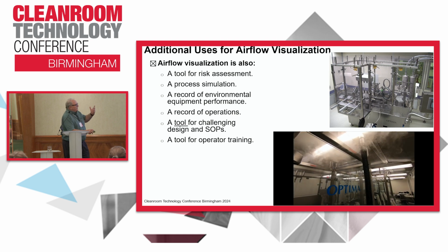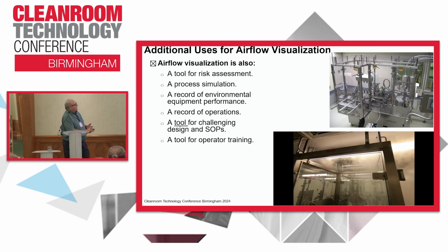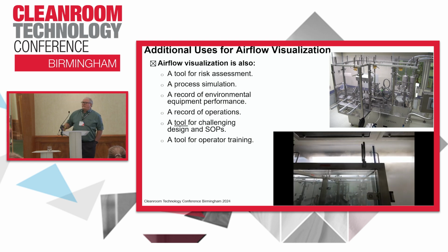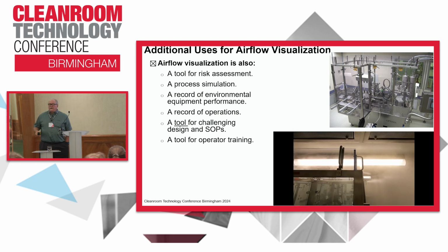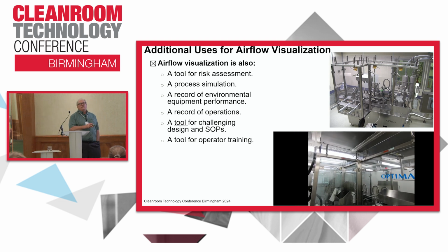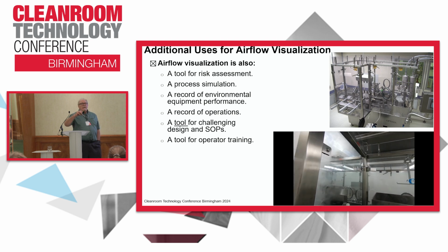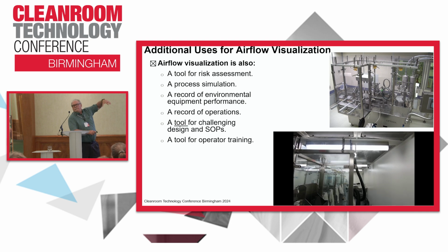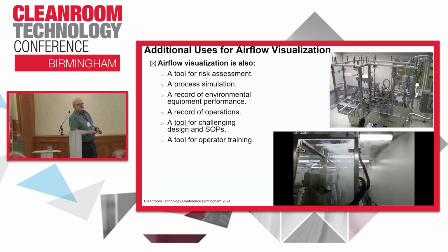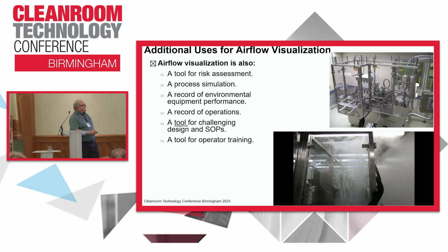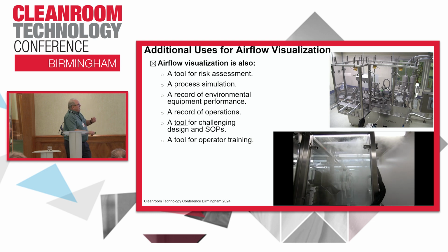In this particular video, here's a company that used an outdated design. If you can see this picture up here on the top of the page, this is an outdated contamination control tool. It's a RABS, right? We talked about Annex 1, but the HEPA filters are not coupled to the enclosure. That is a problem. Every single study that we've been involved in where the HEPA filters are not coupled to the RABS has airflow issues that you have to understand. In this particular case, they didn't understand it, and where we're looking at is the loading pattern, the loading place for sterilized stoppers.